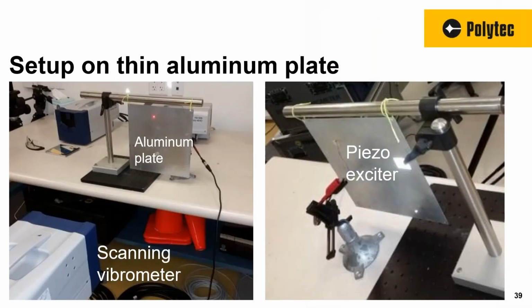And as you can see here in the picture of the setup, we have a piezo exciter on the back, right here on the right-hand side. We're measuring from the front. As you can see here, there's the laser spot, the scanning laser vibrometer head, and we're scanning across this plate, measuring the response at 4,200 points.